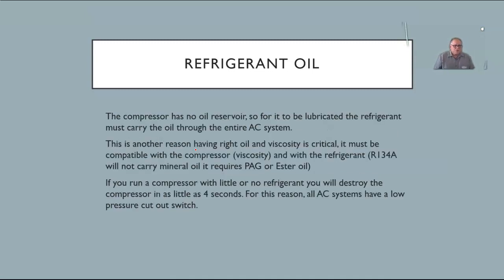So the AC compressor has no reservoir inside of it. Some of the older ones did, the newer ones don't. At least not on the automotive side. On the heavy duty side, yes, they have a reservoir on some of them. So for this reason, it's very critical that it has the refrigerant in order to pick up the lubricant, carry it through the system, and lubricate the compressor. Now, if you start a system up and it doesn't have enough oil or doesn't have any oil, you can burn up the compressor in as little as 4 seconds. So make sure you have the correct charge of refrigerant in there before starting that system up.